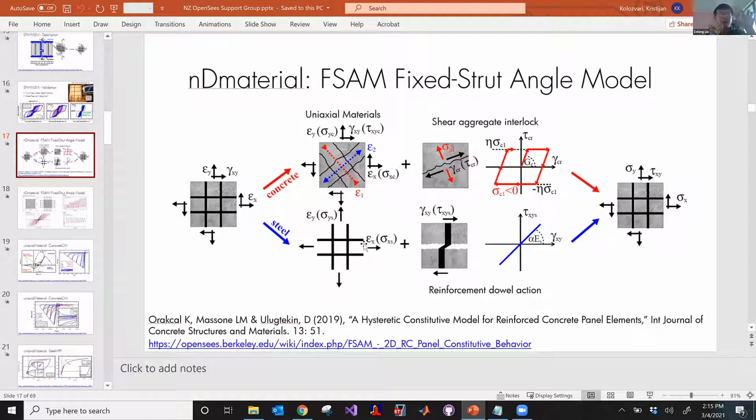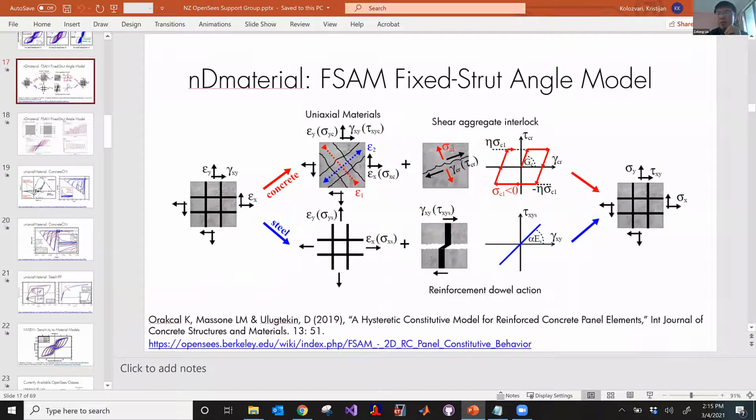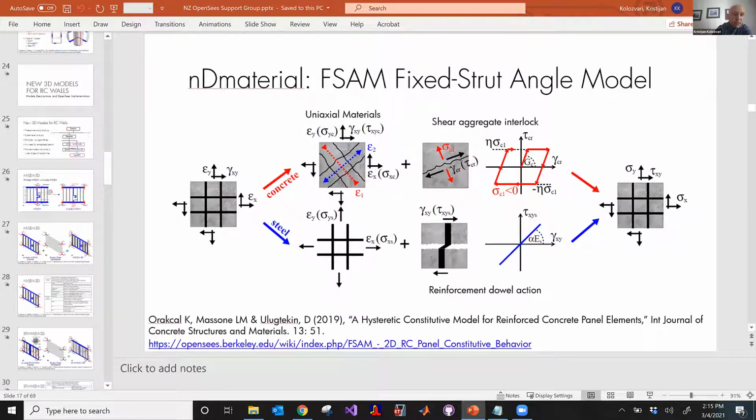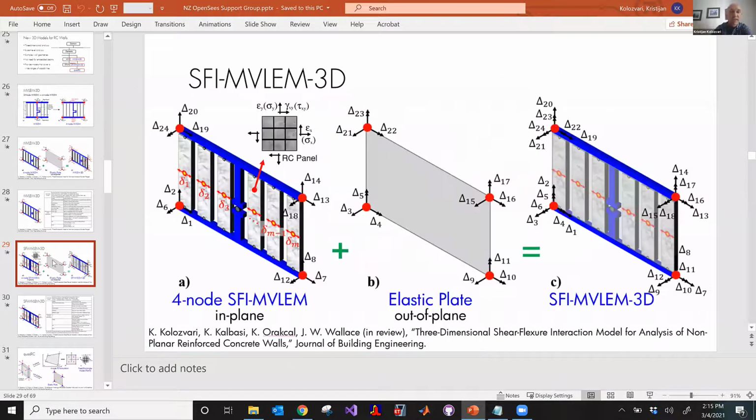Okay. Because I saw there are 4 nodes on the elements. Yeah, maybe you could try to combine that element with some braces or something, but I don't know. I never tried to do that. It's certainly something I would give a shot. It's not that difficult, and I do know that some people trying to model coupling beams with diagonal reinforcement are somewhat successful. Okay, thank you very much.